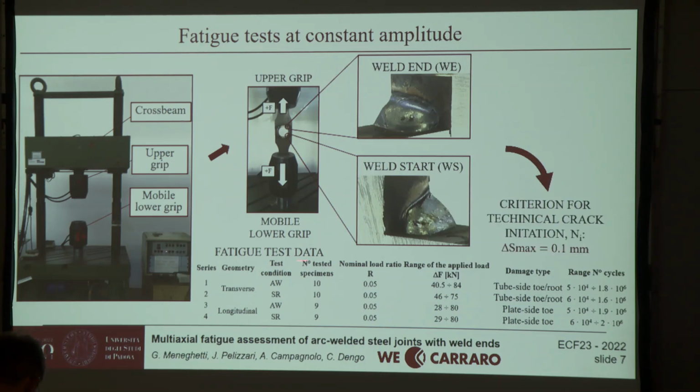The number of cycles to technical crack initiation was chosen in correspondence of an increase equal to 0.1 millimeter of the maximum displacement of the actuator of the testing machine. In our fatigue tests, we have explored a number of cycles ranging between 50,000 cycles and 2 million cycles.